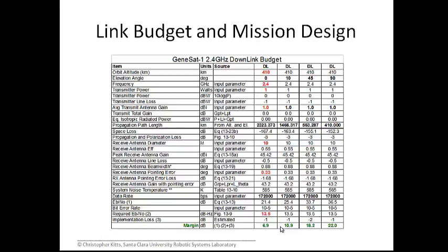And I can play the game of running through different scenarios and trade-offs through the use of a spreadsheet. And in this spreadsheet, you see most of those terms down the left-hand side. In some cases, you see the contributors to the terms, and sort of under the hood, we're computing what the terms are in lower lines. And then in the columns, the last four columns, you see that we're basically running the numbers at different elevation angles with respect to the local communication station on the ground.